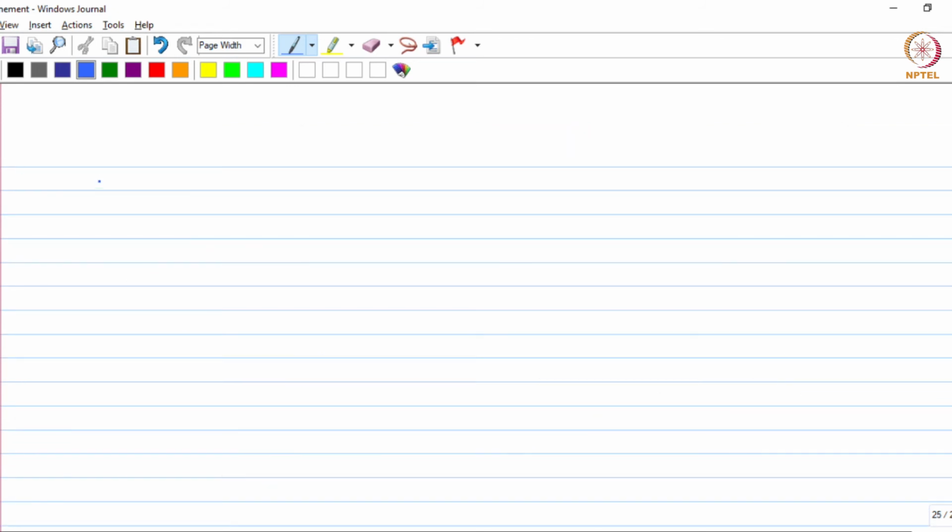So if you talk about this Al3Ti particles, that is the titanium based grain refiners, these particles are generally faceted and therefore the number of faces or number of facets on which aluminium can form will be more in a particular type of morphology, right?